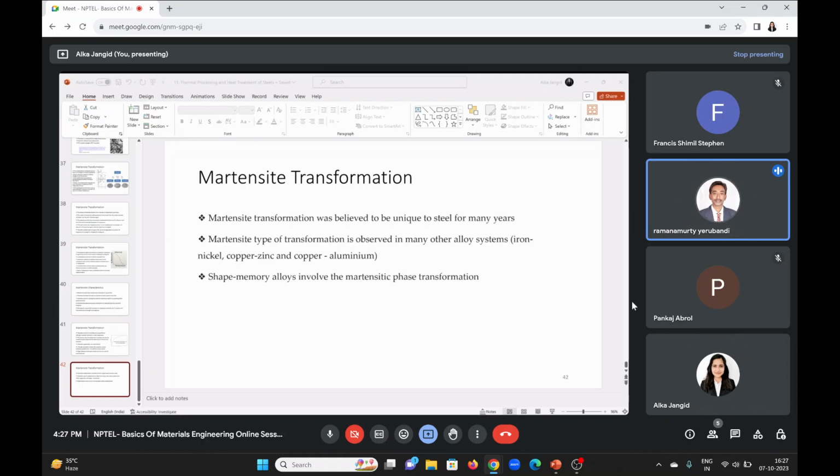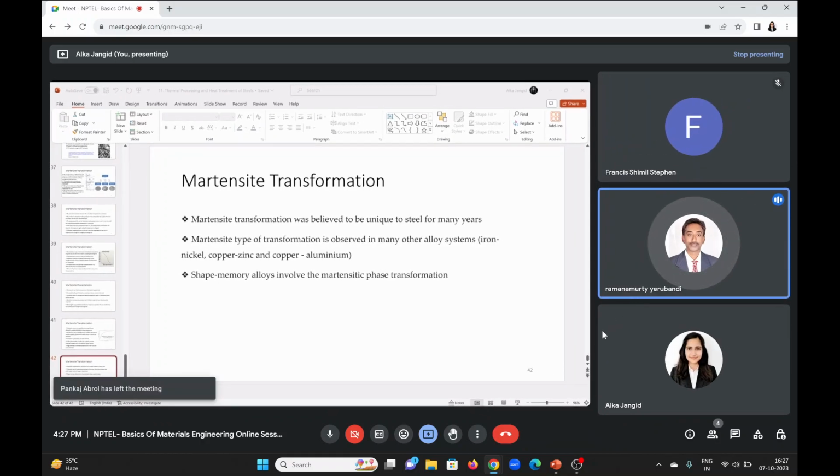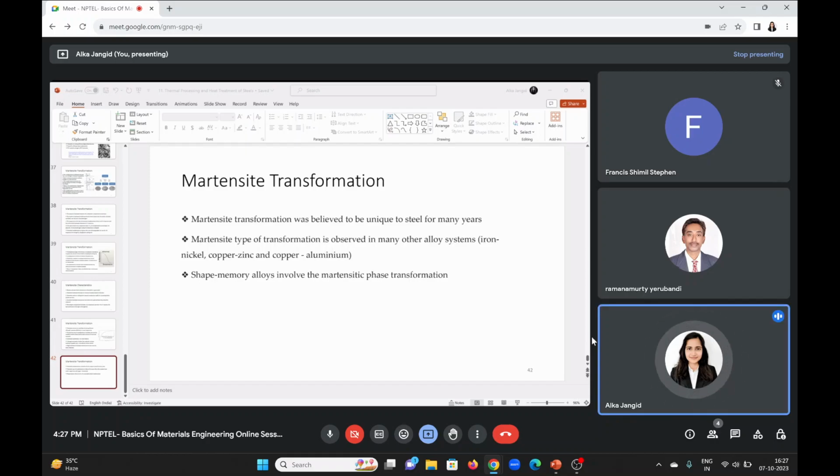Can we use stainless steels with carbon content of more than 0.8%? Yes, in stainless steel you can use carbon content of more than 0.8%, like a hypereutectoid steel. In the case of certain stainless steels, carbon is seen as an impurity, so in many steels you keep it lower than 0.2%. But in some stainless steels, you can have a high carbon percentage as well. It depends on what properties you require.